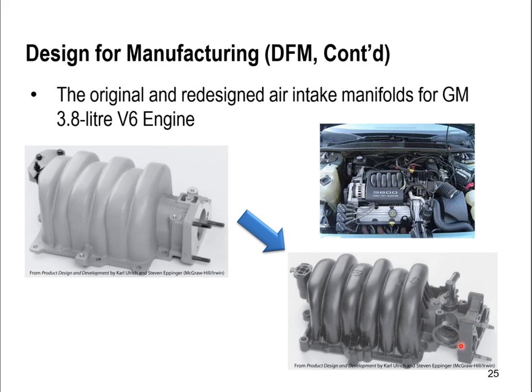This definitely was a part of the design, but it was an individual part to be assembled here. And thus, by joining the two parts together, we not only reduce the cost of manufacturing between the plastic and the aluminum, but also we reduce the weight, because the different materials have different properties, like the lighter material is going to be much better for the performance of the car in general. And in addition, the energy used to manufacture the plastic was less, and we joined the two parts together to reduce the cost of the assembly.